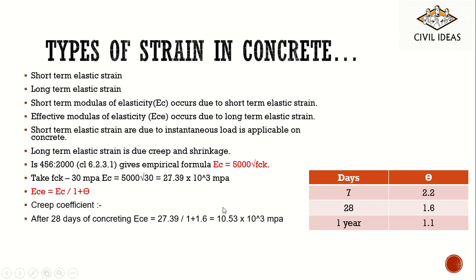Now, if a concrete is already cast and you want to find its effective modulus of elasticity after 28 days, put theta equal to 1.6 in the above formula. You will get the effective modulus of elasticity as 10.53 into 10 to the power 3 megapascal.